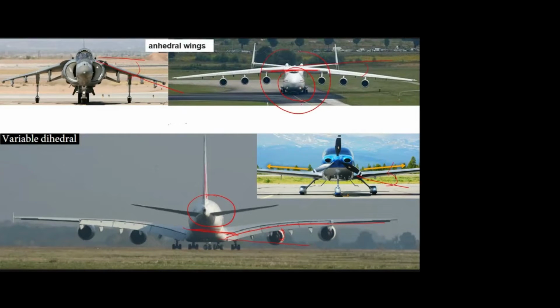But if it is a cargo aircraft, the weight will be more, so we have to add more engines, and we have to give some clearance. So mostly for very large aircraft, it will be a high wing, a very stable configuration. So it will be very difficult to do little maneuvers. In that case, to introduce maneuverability, they use the anhedral wing. Is that clear? Okay. So only in fighters and the high wing configuration do we go for anhedral. In other commercial applications, we go for dihedral.